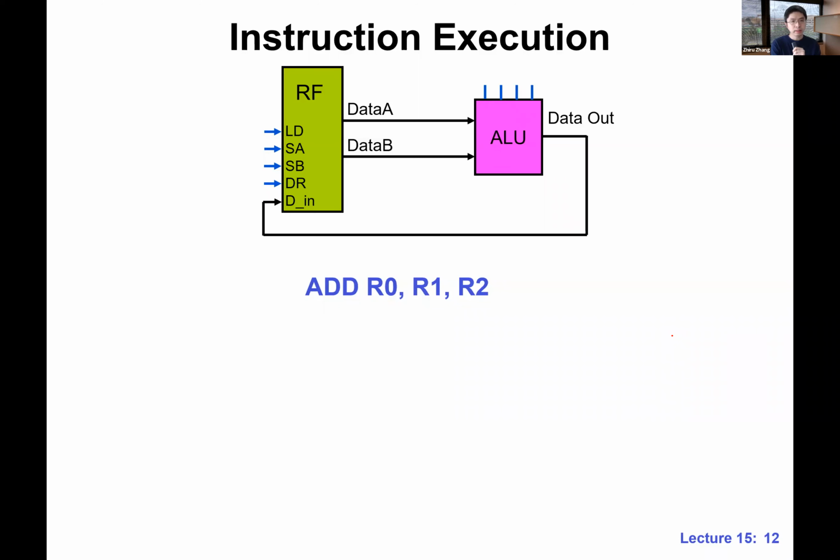Okay, so now that we have this register file and the ALU, we need to tell the processor, this basic processing unit, what kind of operation we want to do. I want to remind you guys again, what we want to do is (a plus b) times (b minus a plus 1). This is the expression that we want to compute. So let's first try to compute this one, a plus b.